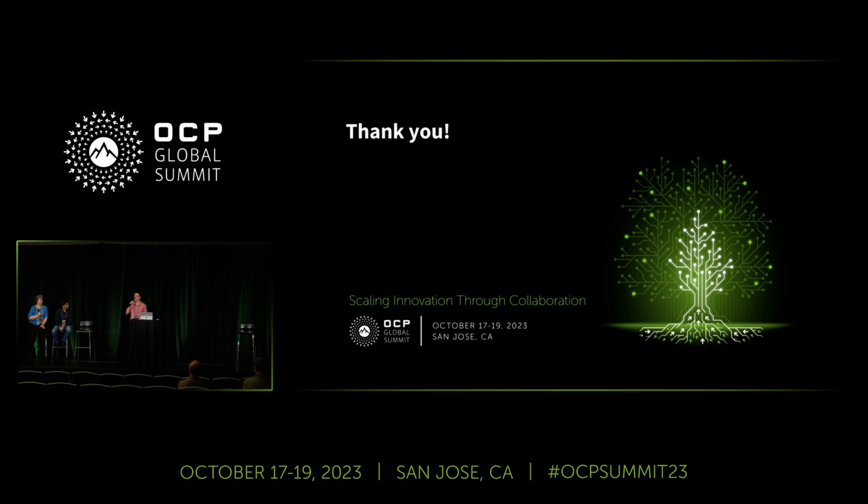And if I had to put it into groups that aren't aging, I would say test escapes are one, where it makes it to production just because we didn't hit it, bad luck or lack of coverage from the tests run at manufacturing and system integration time. So that's one class. And then another class is early life failures, where you have something usually within the first 6 months or a year of production operation where you have a defect manifest, but it's not the same fault modes as an aging case.